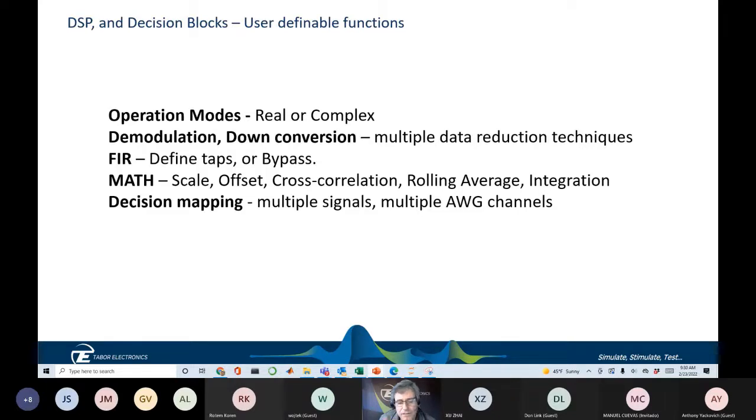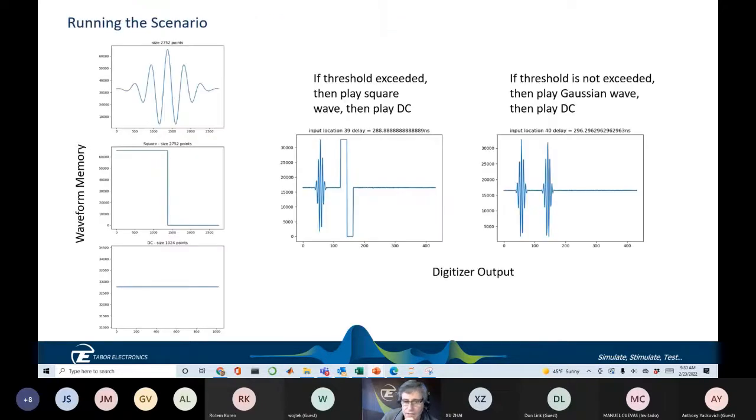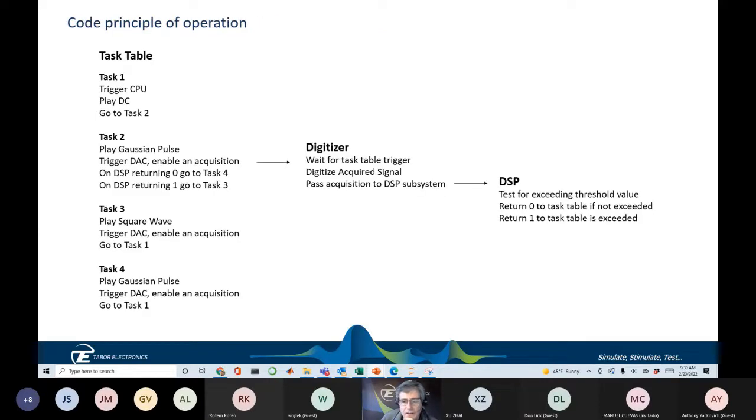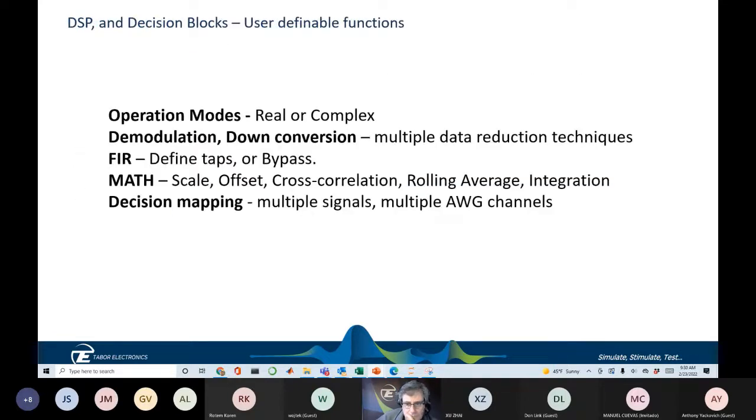So the digitizer not only controls a single channel, which I showed in this example, you can have this decision control different channels or different modules within the same PXIe modular system that the arbitrary waveform transceiver is embedded in. That's a key thing as well. So you can make one measurement and control, say, 16 different waveforms or 16 different channels.